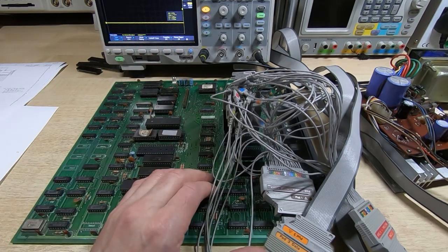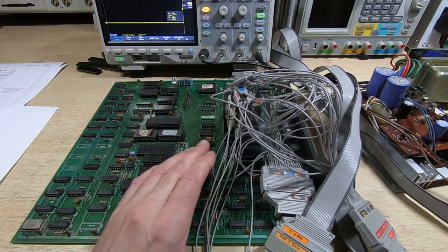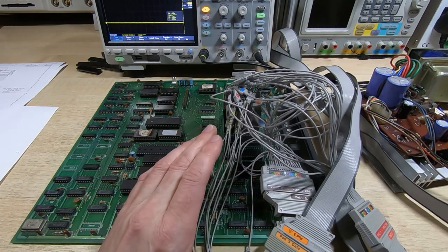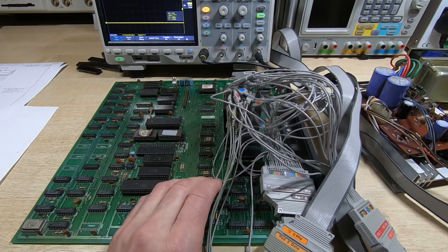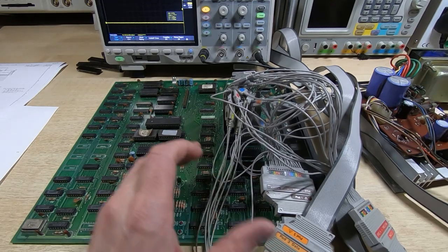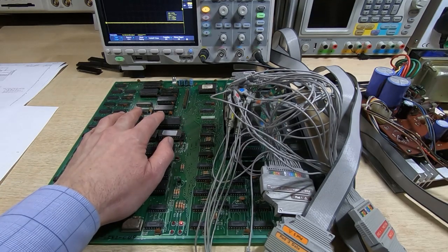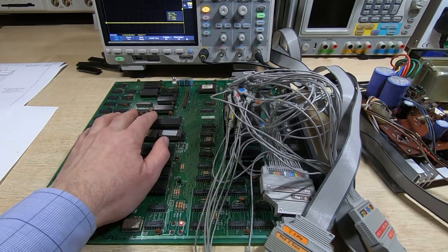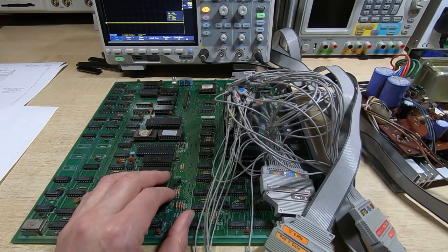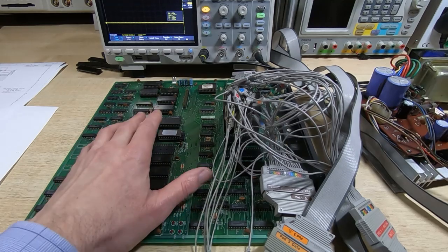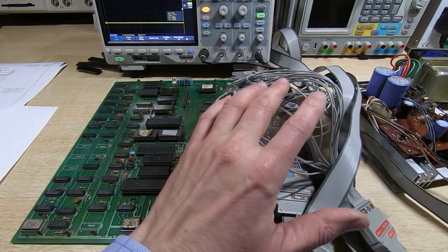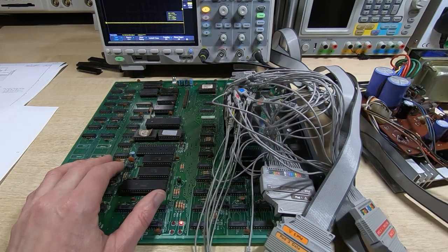They are brand new DRAMs, so I know they all work, so it's not that. Did have a stuck bit when I first started trying this, and hopefully we can figure out fairly quickly why this self-test is failing, and then probably move on to the next. The 6502 doesn't run either, so we'll need to treat that as a separate repair almost, but the first thing I want to do is get the Z80 at least running to a certain extent, so that it's not going to hamper the 6502 repair when the 6502 is interrogating the Z80 for information.